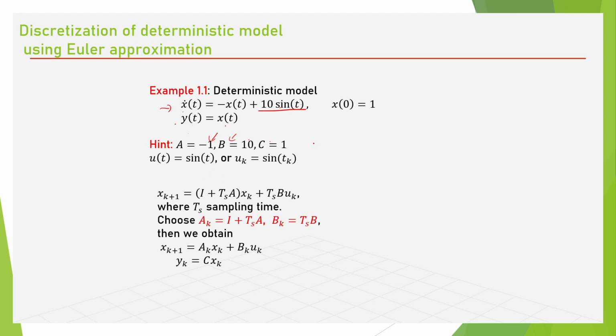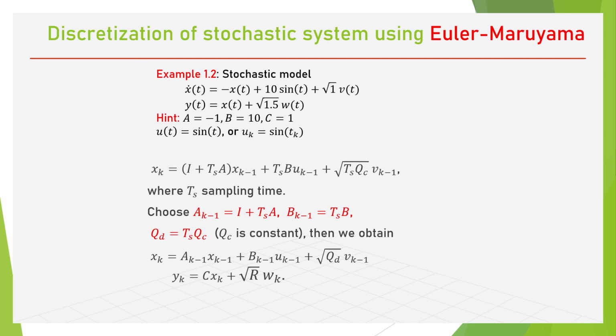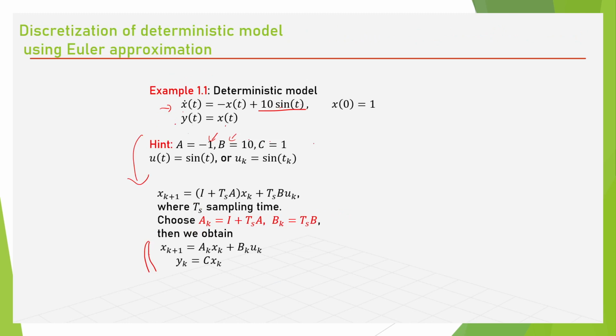And then we do the discretization for computation, using the Euler approximation to get this discrete model. Then we can implement the Kalman filter directly. This is just the deterministic model. When we compute it, we get a nice pure sine wave like that.